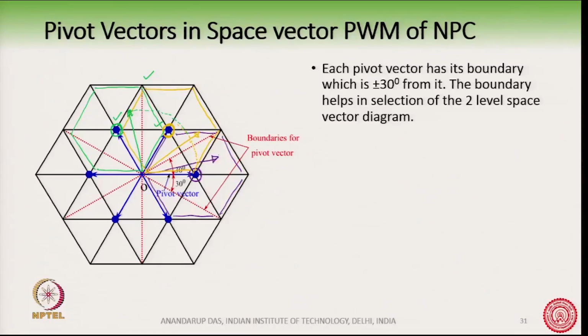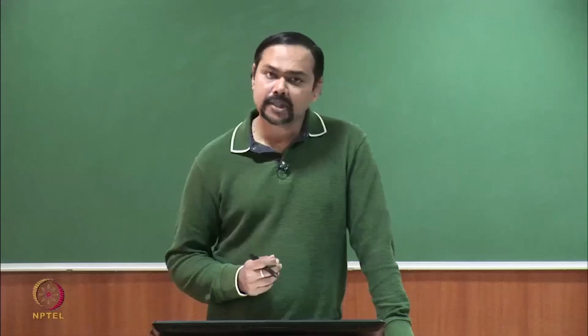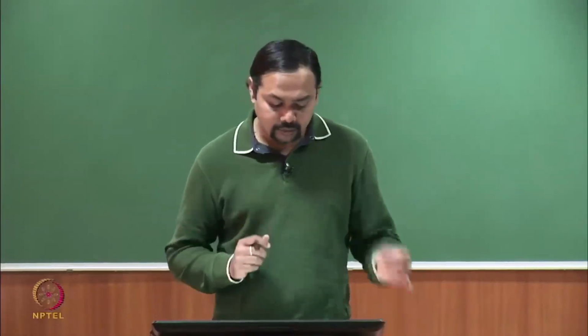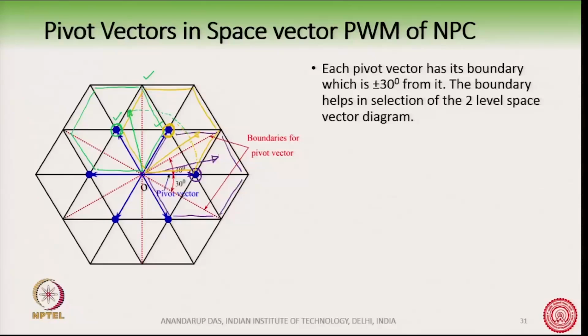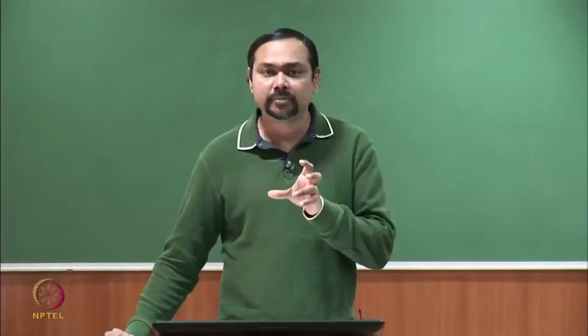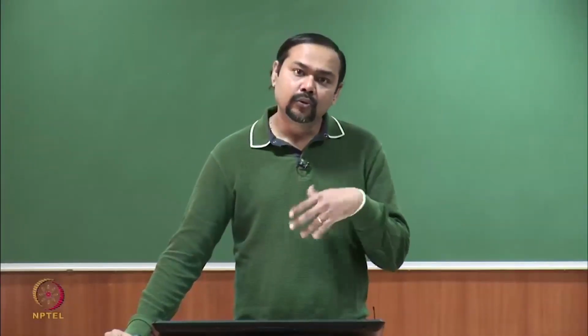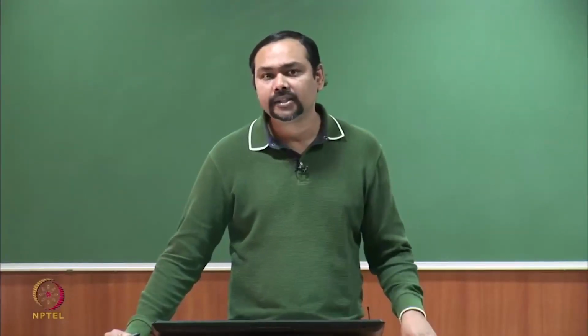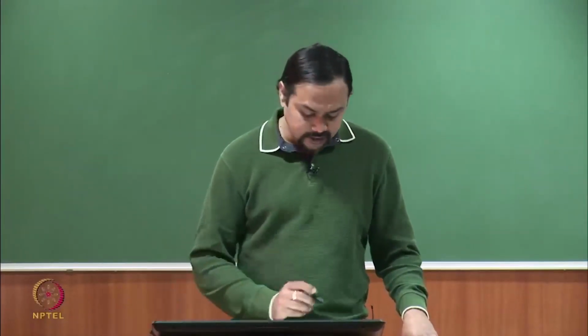Of course, we can do this by carrier based PWM. We do not have to all the time multiply these and get the mathematical expression; that is not needed. We can do it with carrier based PWM, but this is how the actual switching takes place inside the space vector diagram.